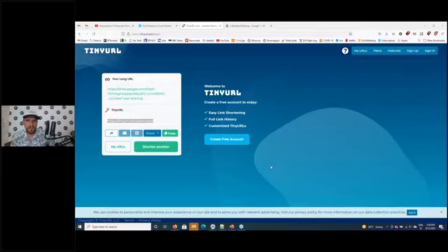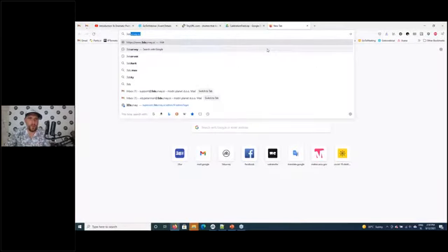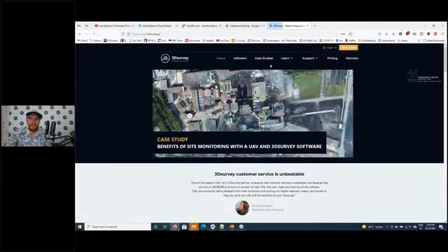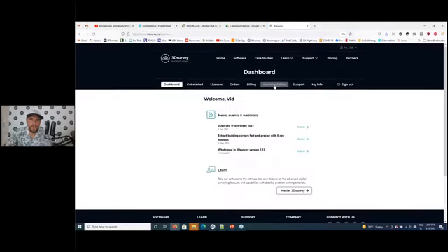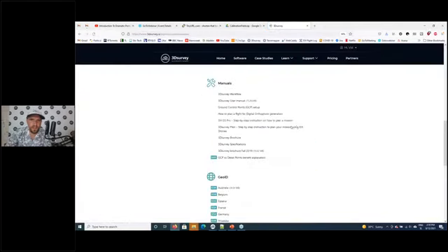If you do a mapping of a building facade, it might help if you place some of these dots, some of these ground control points, on the facade and measure them with the total station, for example, so that you will be able to georeference your house model. If you want to do that, go to our webpage, sign in, go to the downloads section.